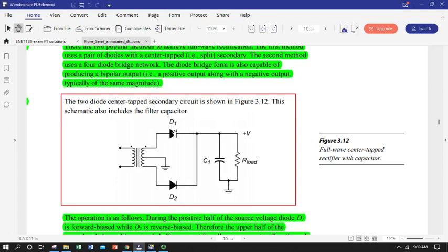Positive current could try to flow back through the diode, but it can't because the diode is now reverse biased, so it acts like an open. So again, it has no choice but to flow the same way to the output circuit, continue to charge the capacitor and flow through the load. And back we are, one full wave cycle.